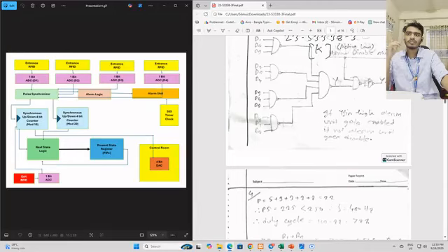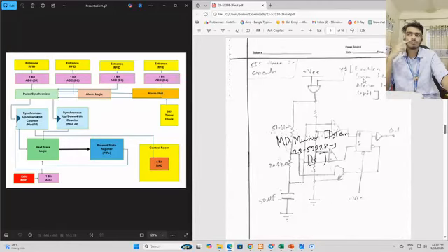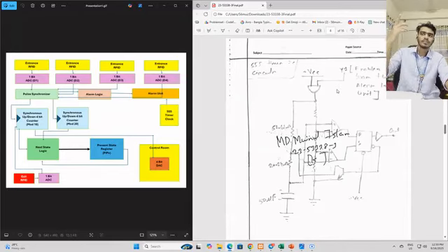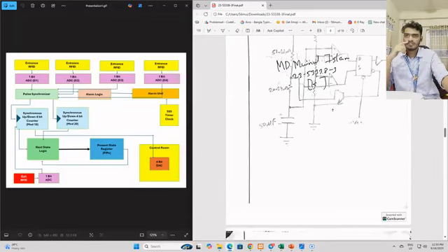If you want to disable it, we can use this manual switch. That's why I have added it with an AND gate. If we get the signal that the alarm should trigger, it will turn on the alarm circuit. If it goes off, then this will turn off the alarm circuit. So this is our 555 timer IC.